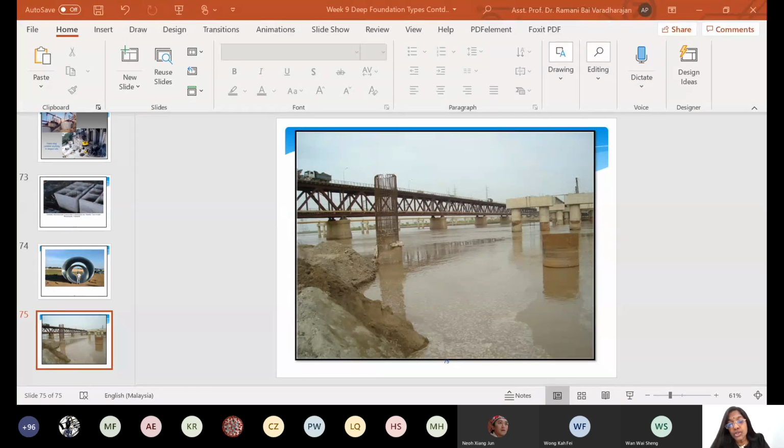Beneath the surface, it is going to be a deep foundation like piles. The caissons might be supported by piles. Otherwise, throughout the section, it may be caisson depending on the height. Sometimes, like highway flyovers carrying 3-4 tracks, it may be piles continued by caissons on the ground.